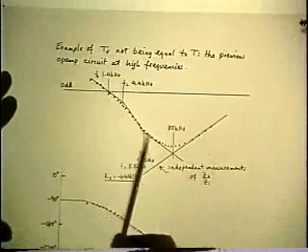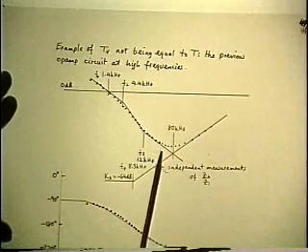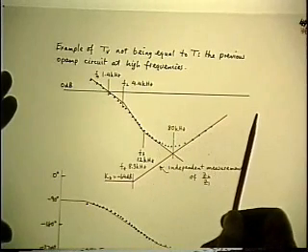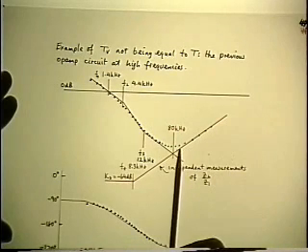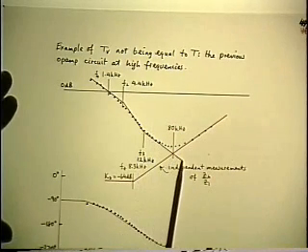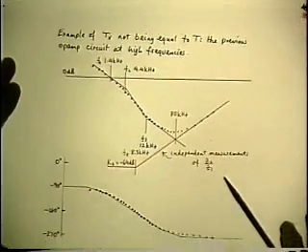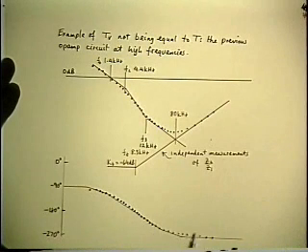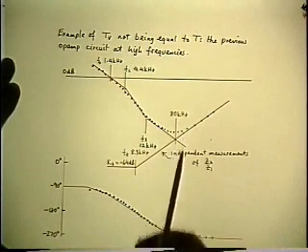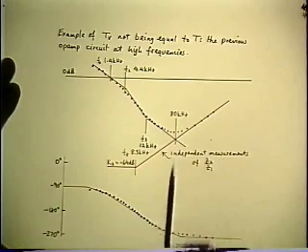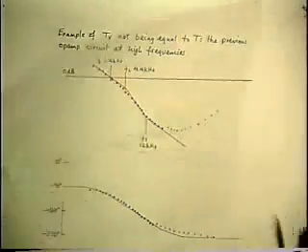Because it explains why the measurement of T sub v started to deviate from T at 81 kilohertz, and it turned around according to a double real 0 at the same frequency. So at that frequency, the -1 slope was changed to a +1 slope. But it also explains why there was no change in the phase. Because the only difference is a right and left half plane 0 at the same frequency, and the phase contributions cancel. One's a lead and one's a lag at the same frequency. So that is now a full interpretation of the measurements.